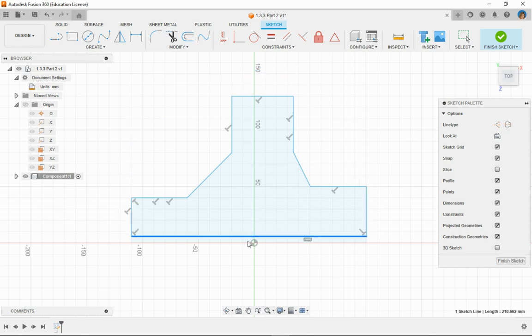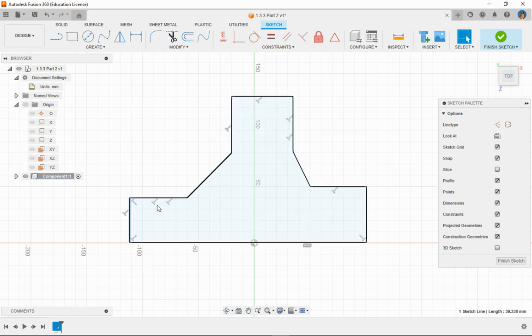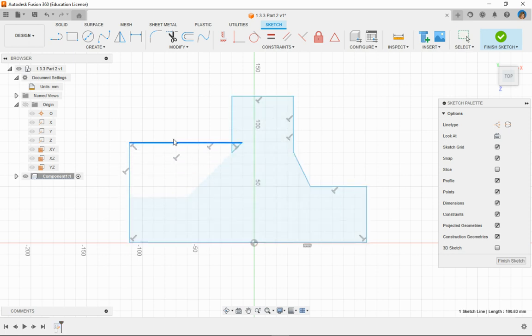So this is horizontal. Notice it stays horizontal whenever I move it. Okay, perpendicular. Depending on what it's perpendicular to. In this case, we said this is perpendicular to this one, so anytime I move this, it should always stay perpendicular to that top line. This line here, which is 3, is perpendicular to 5. So whenever I move line 3, it should always be perpendicular to 5. This does not have any constraints on it, so it's going to do all kinds of weird stuff. So play around with it a little bit.